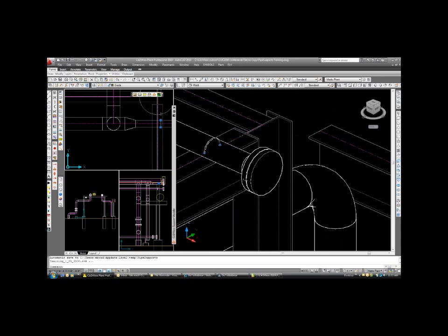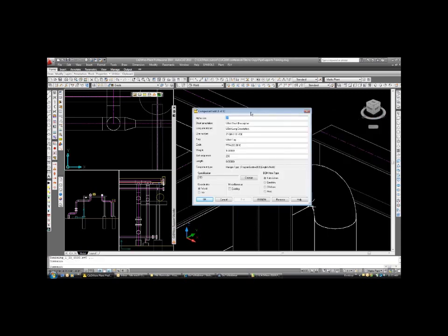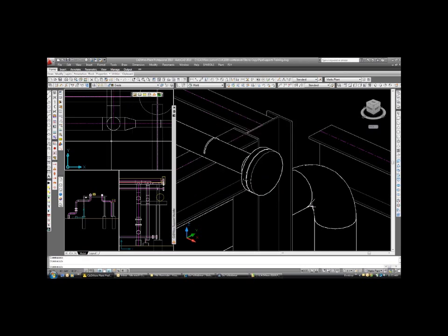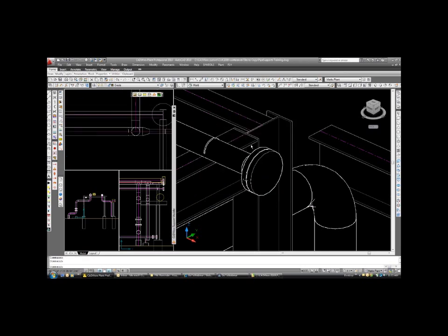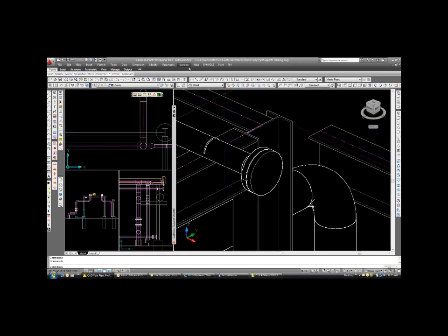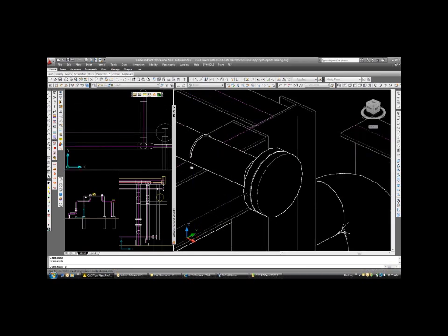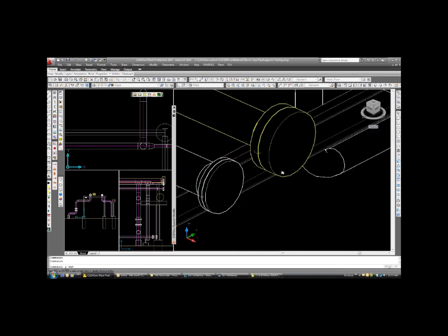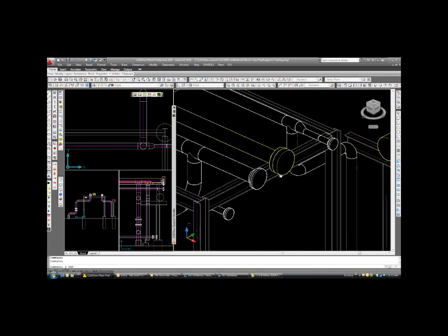And if you click on that U-bolt, there's our long description, and our line number it selected was the 3-inch. It gives us a tag and a length. Everything you expect to see in a bill of materials. Okay. That basically is how you insert a particular pipe support